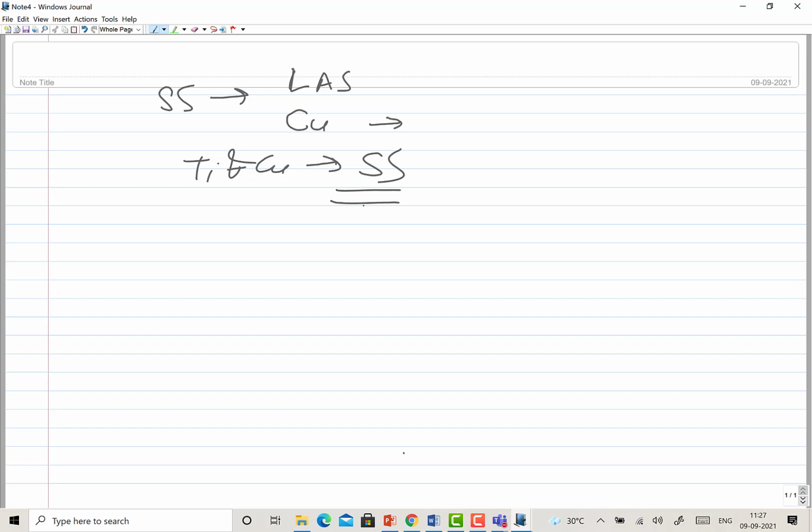You may need here, in some of the cases, a transition joint in between. So a transition joint is nothing but, say with two metals, SS and titanium, in between you bring a third metal which is compatible with both the metals. So to deal with metallurgical compatibility related issues, or to deal with differential thermal expansion coefficient related issues, we need to bring in either interlayers, or a small piece of metal as a transition for developing the transition joints.